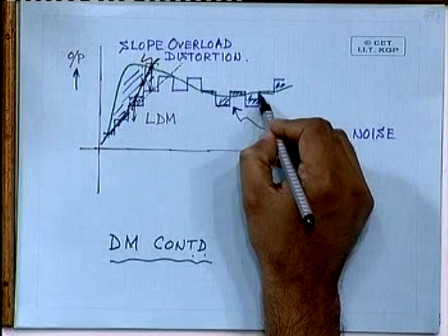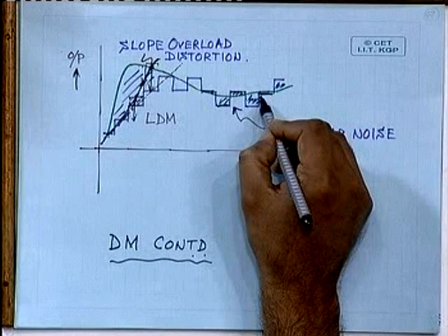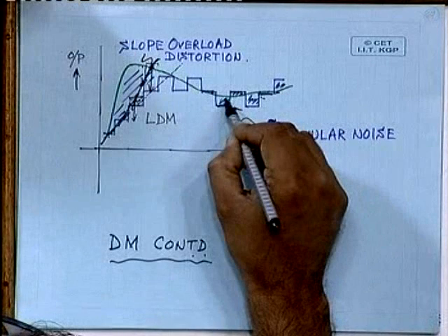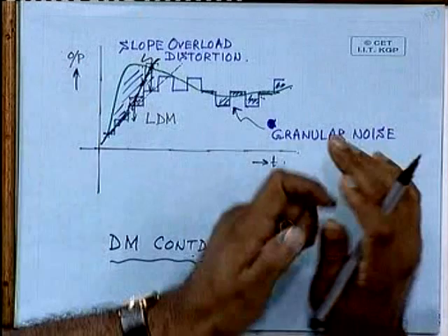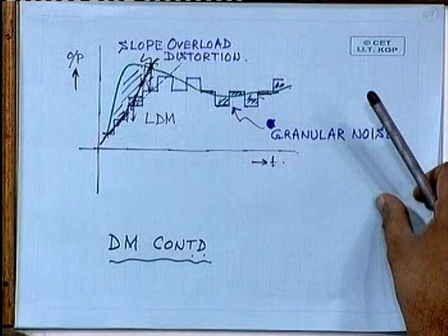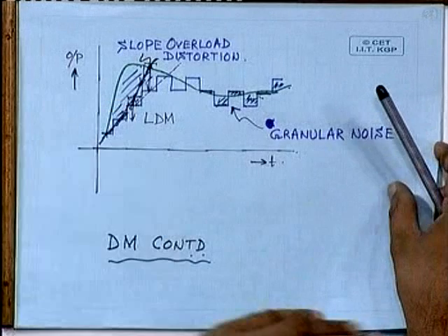If it does not, or if the polarity is the same as this one, then you would like to reduce it further. Like that you can very approximately track the input signal, and as a result the overall quantization error can also be reduced. So summarily, if you go for the adaptive delta modulation scheme compared to the linear delta modulation scheme, you can expect an overall improvement in signal to quantization noise ratio. But anyway, we will continue with our discussion on linear delta modulation.